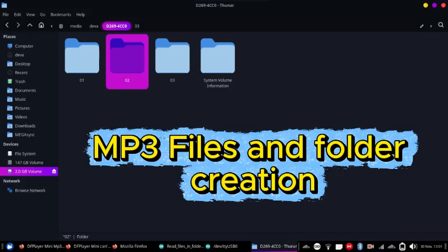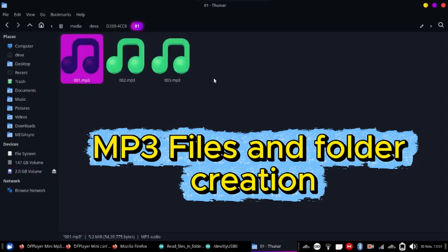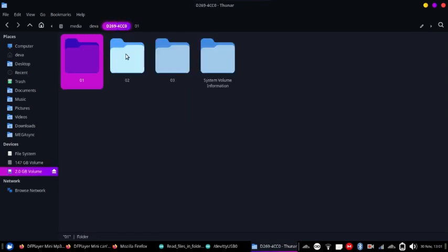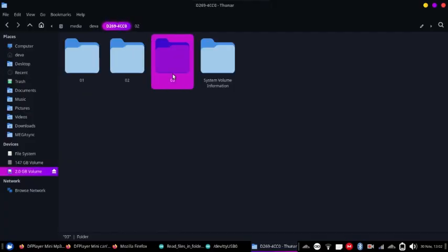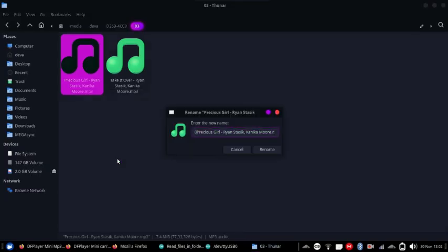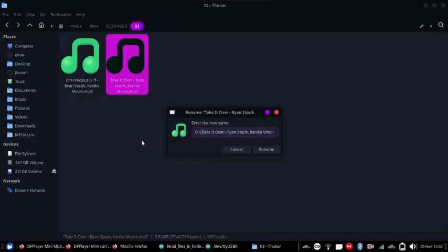Before wiring, prepare your microSD card and format it in FAT32. Create folders, or you can simply drop the files in the root. I'll be showing you how to access it from folders. Rename your folders as 01, 02, 03, etc. and put your MP3 files in them with the naming like 001.mp3, 002.mp3, or if you want to name it in English, you need to give the numbers first and then you can add the rest of the song's name or whatever you want.